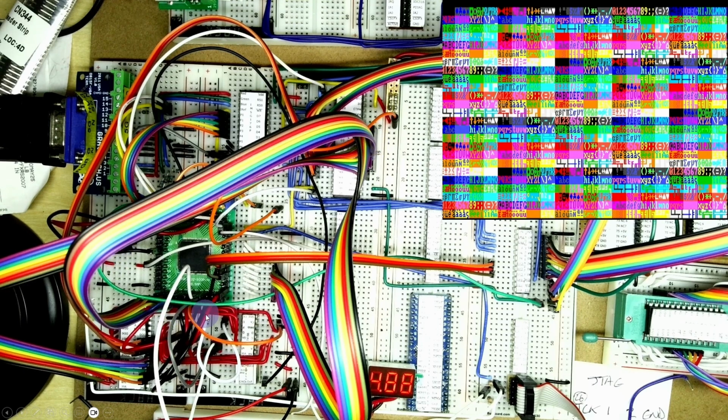So in this video what we're going to be doing is looking in a little bit more detail at testing the video attributes. So things like the blinking, the 40 column mode as well as the 80 column mode. And we'll also be looking at the control mode register and the status register to make sure those are working. So this is the pattern that was produced in a bit more detail, and we'll be looking to see if we can repeat the pattern that I showed from version 1 of the series, where we had this pattern with the thinner band, so we'll be looking at that.